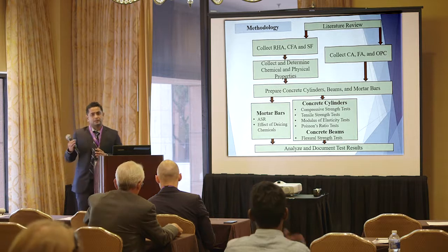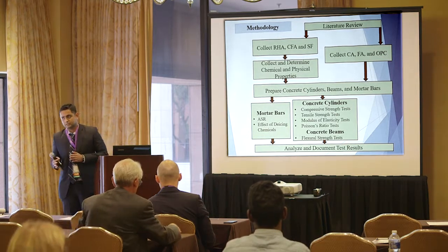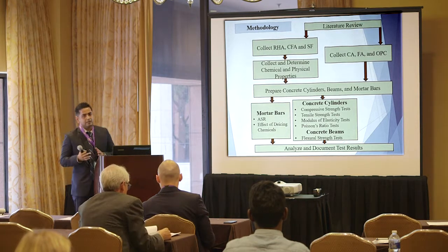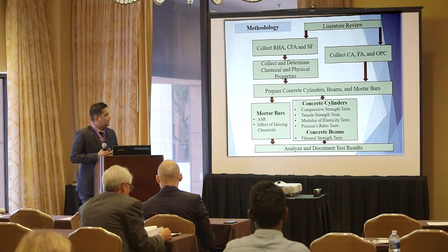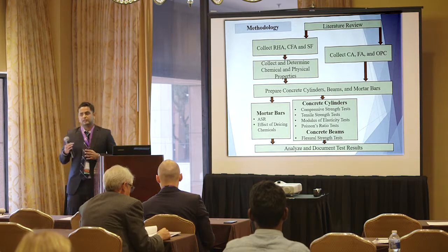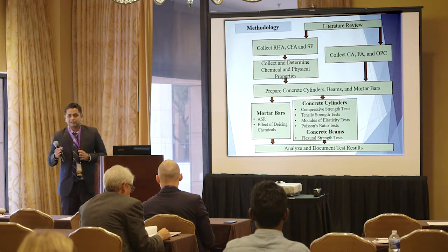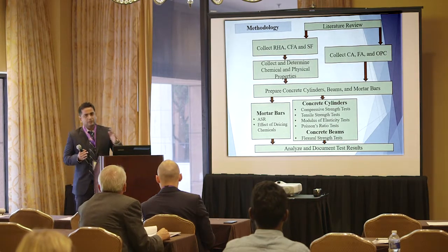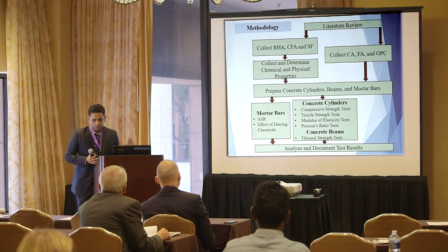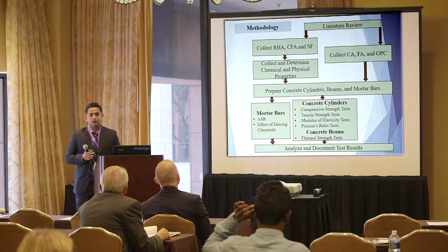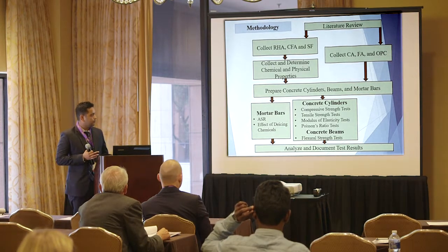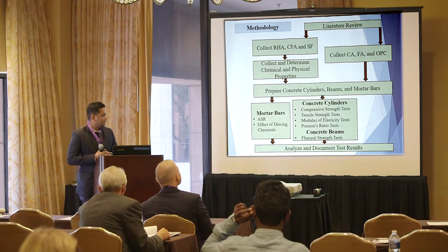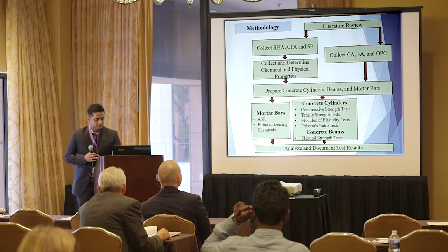This is the methodology I followed for the whole procedure. I collected the RHA from different sources, along with CFA and SCW, then determined the chemical and physical properties, then prepared the cylinders, beams, and other specimens with this modified concrete. Then I tested them, following the basic concrete tests to see how this modified concrete performs. At last, I analyzed and documented the test results.